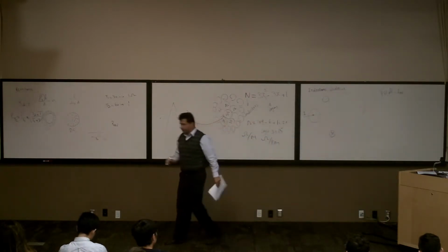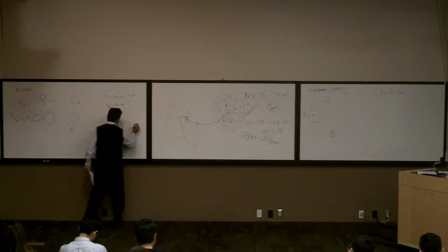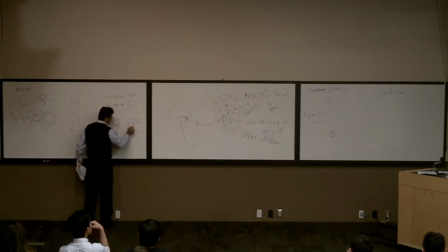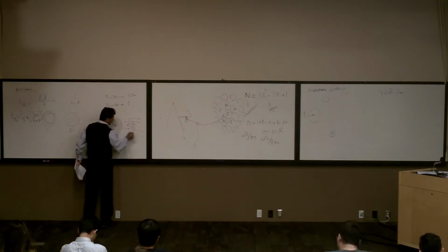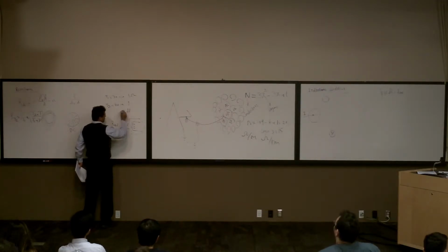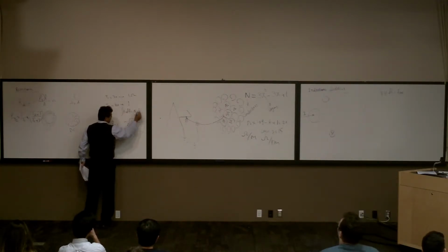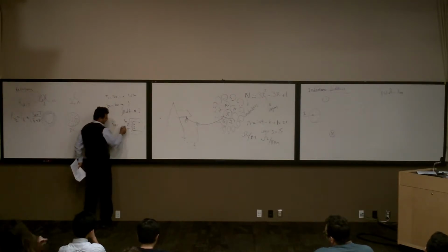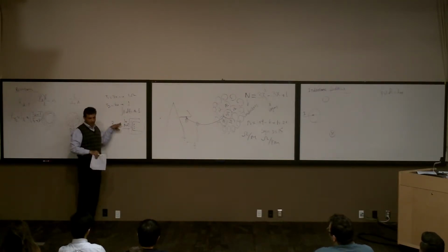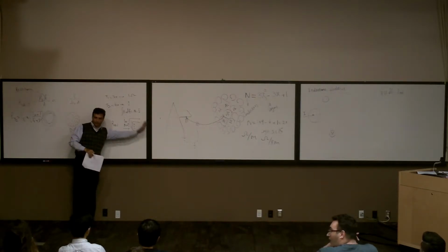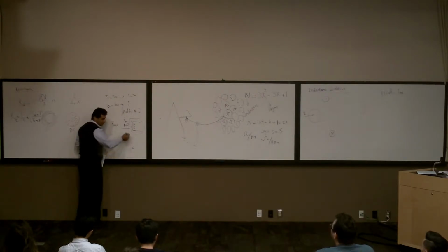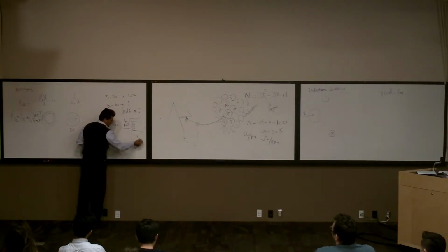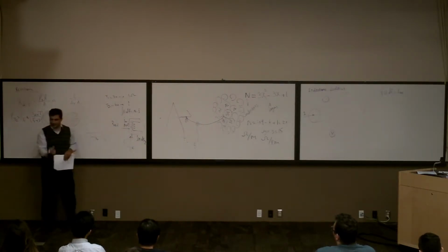Wherever we consider the loop, for example, in the transformer, if you write the H dl around the loop, it is going to be NI, because this current is I and we have N of them, so the current inside the loop is N times I. But when we had only a single wire, H dl was just I, because there's only one current going that way, right?